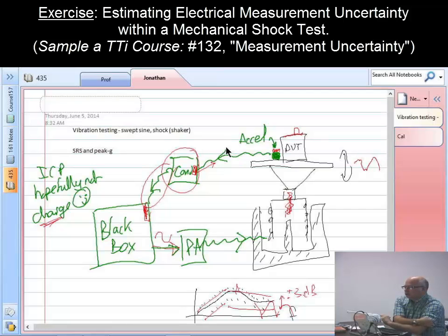One of the things that we do get is a triboelectric effect. The cable is being bounced around at the accelerometer end and is stationary somewhere, wherever you've brought it off the shaker head, so the cable is being bent. There is internal friction in the cable, and that can generate a charge that is correlated with the signal. That's why we tend to like these low noise cables, with graphite lubricant and such, to reduce that. But generally speaking, if you've got ICP conditioning, it is fairly robust, and you don't usually pick up very much of that problem.